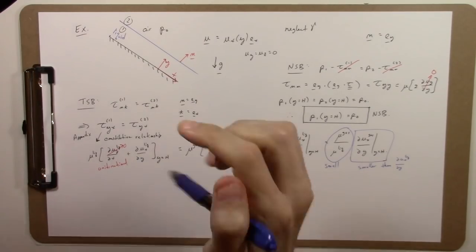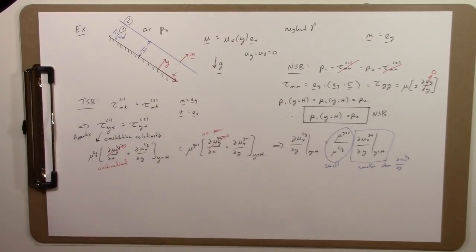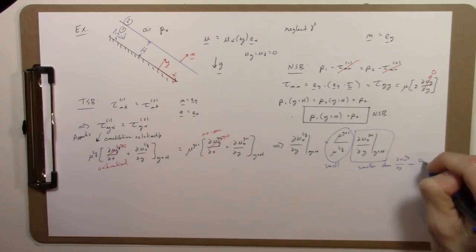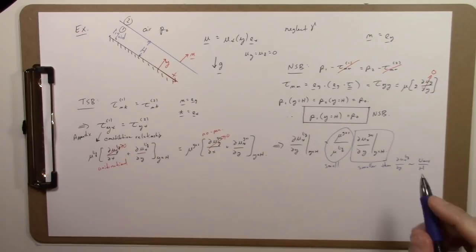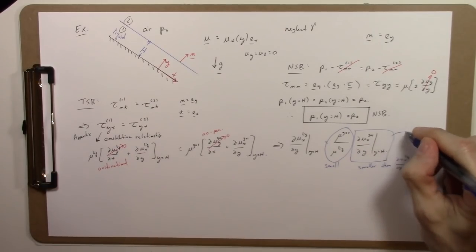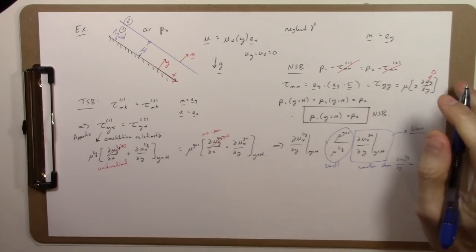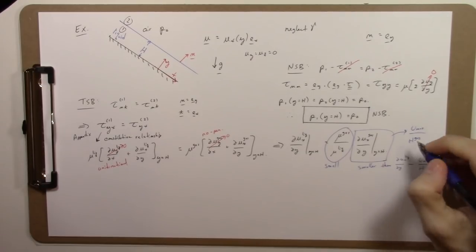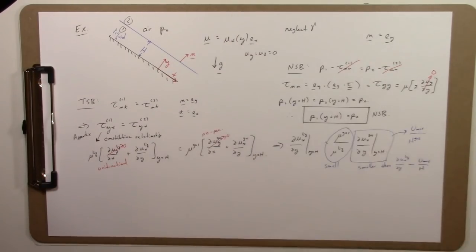Let's say this thickness is capital H. So du liquid dy is roughly u max over H. dux gas dy is roughly u max over something we call H gas, and H gas, the thickness of the gas layer, is much bigger than the thickness of the liquid layer.